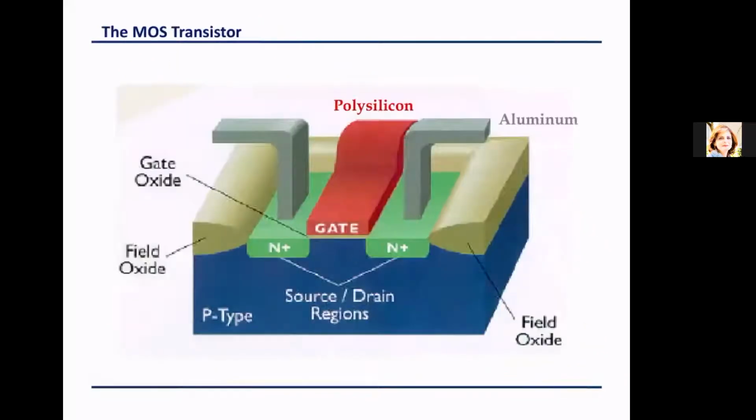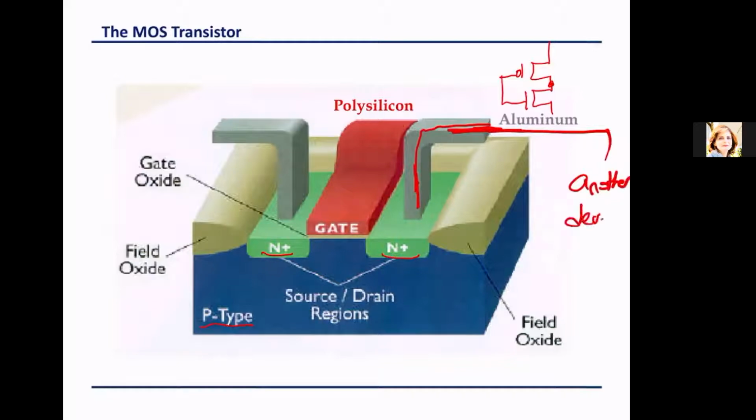So let us now look at this very basic picture of a 3D image of a transistor. The 3D image of the transistor has the P-type substrate. We plant the source and the drain region. When we connect them to the signals or to other transistors, right? Because, for example, in an inverter, the NMOS is connected to PMOS at this node. So this node here is going to connect to another transistor, right? So this may go to another device, this may go to ground, and so on and so forth. And the gate will have its own connection.